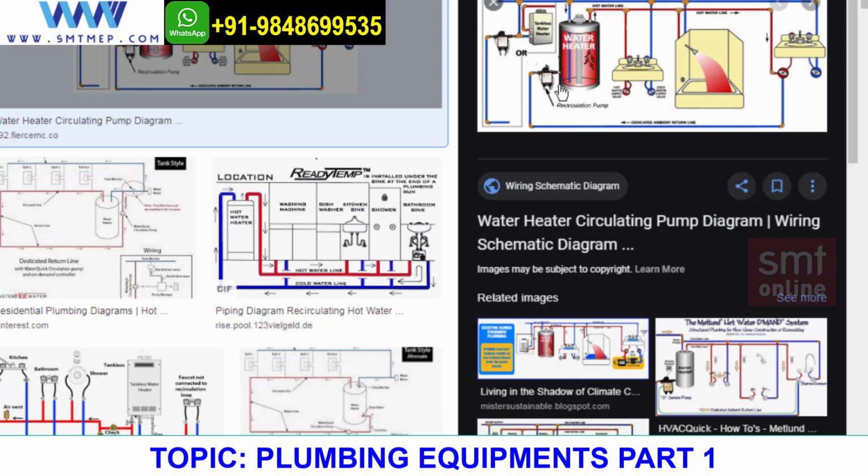What a hot water circulation pump does is, it will be connected in this line, in this hot water line. It will suck the hot water in this manner, pump it in this way, and again pump the hot water into the heater. Why so? While the water is transferring from here to here, I'll have bathrooms over here, and so on. So anyone who calls for hot water will get hot water at the very instant.